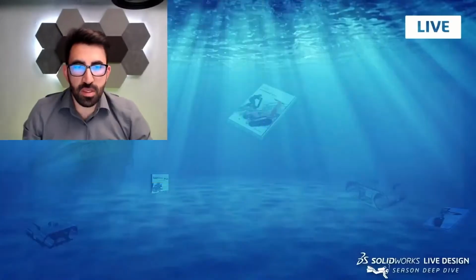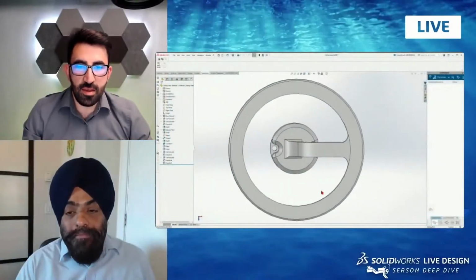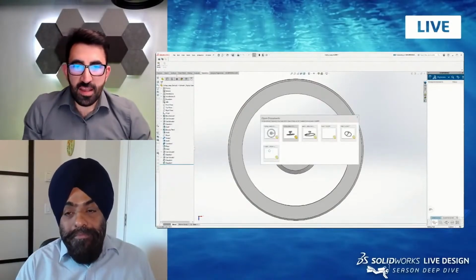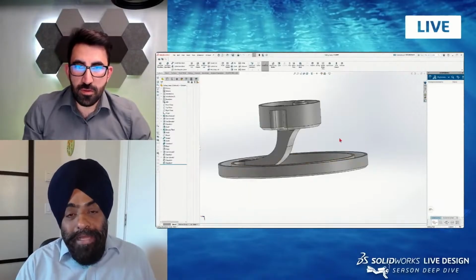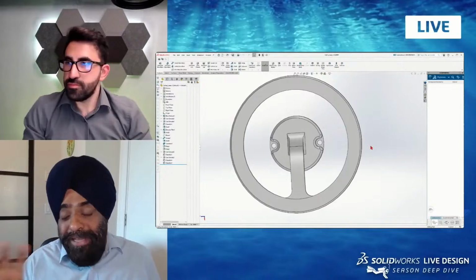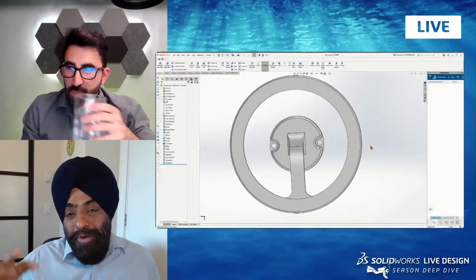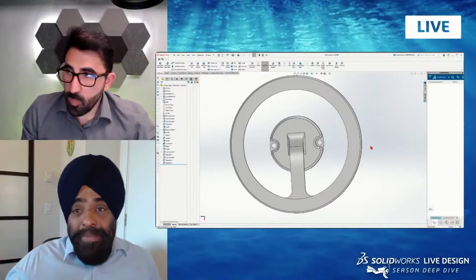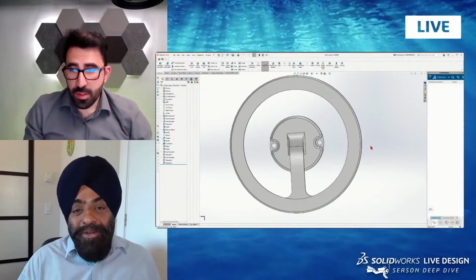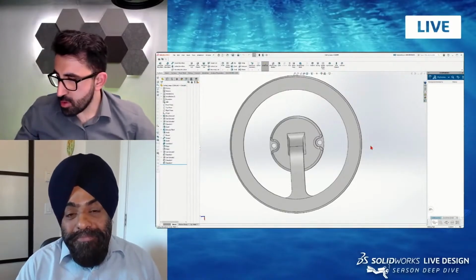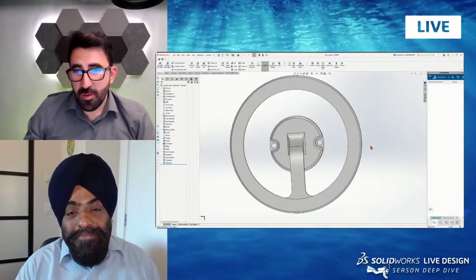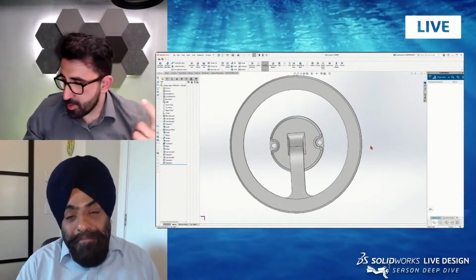If I had spent more time looking at my design, I would have noticed that this hole that you're seeing on my screen is actually hidden behind the bridge. So I had to go back and end up on this. You can categorize it as an issue from the design for assembly perspective, where I was not able to assemble it because of the design issue. Yeah, absolutely. This is something that I knew, and I did not follow myself. So it's happening.